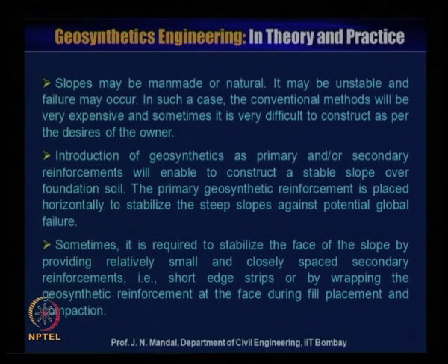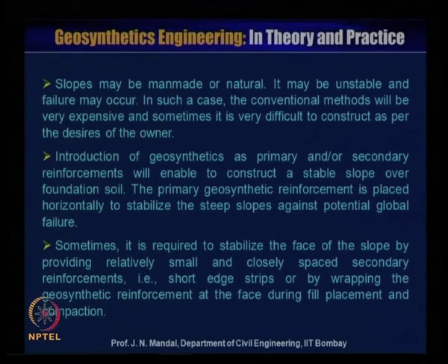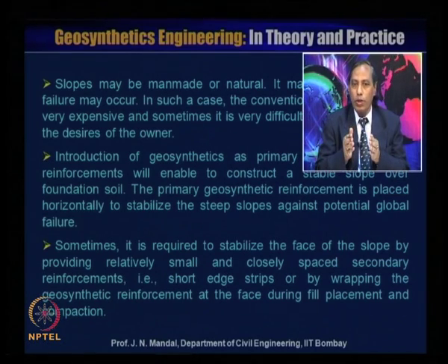Introduction of geosynthetics as primary and or secondary reinforcement will enable us to construct a stable slope over foundation soil. The primary geosynthetic reinforcement is placed horizontally to stabilize the steep slope against the potential global failure.